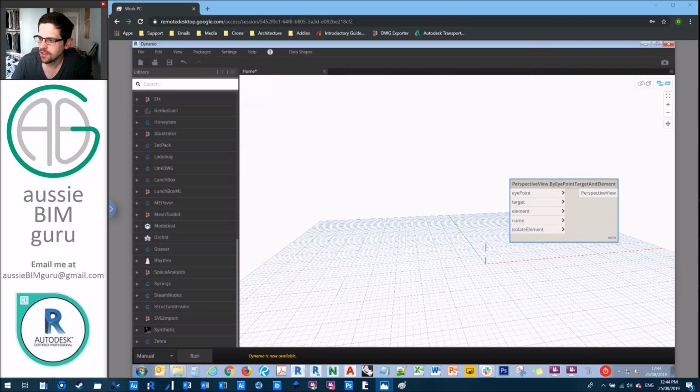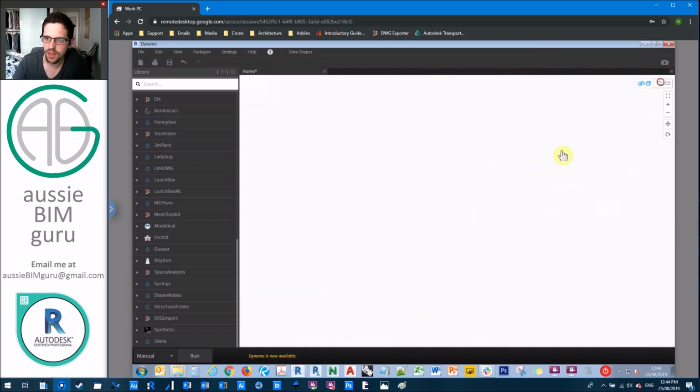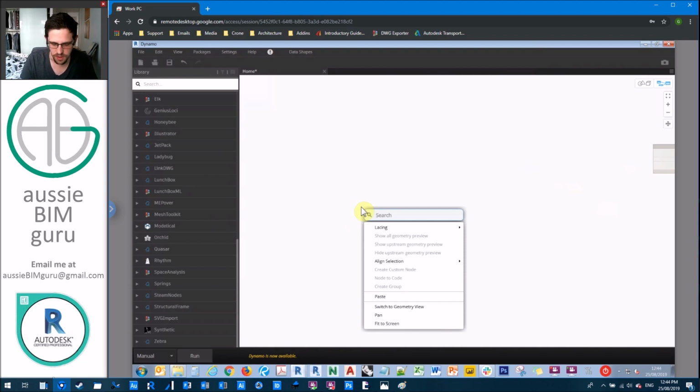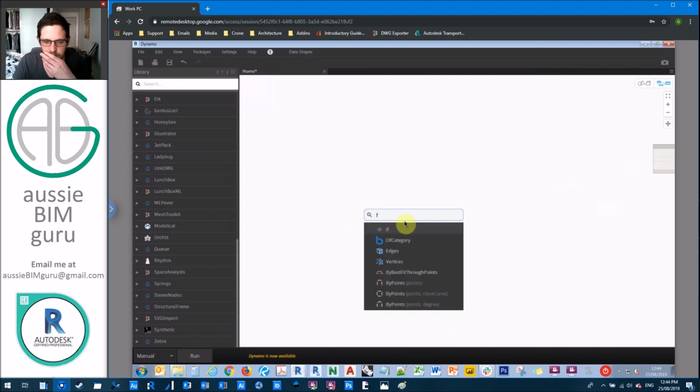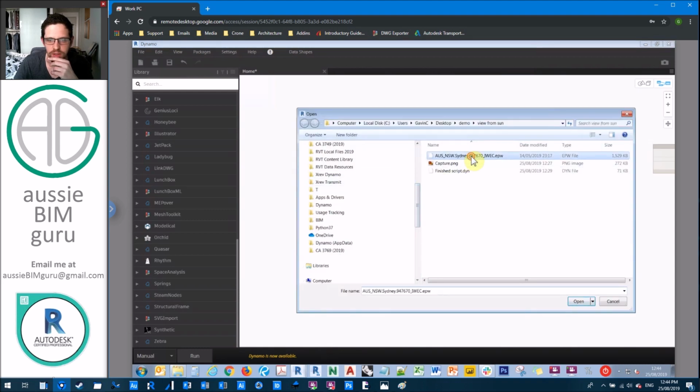Anyway, we're going to go back to the start of the process. So we're going to set up our sun rays using Ladybug. So I'm just going to move all of this off to the side. So what we need to do is get the rays of the sun from Ladybug. So we need to get our EPW file, so we need a file path to do that. So I'm just going to go file path, browse, and we'll just browse to our weather file.